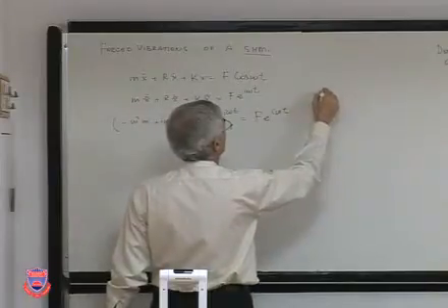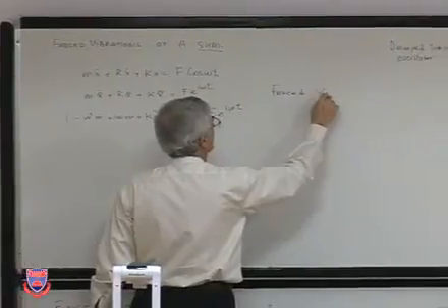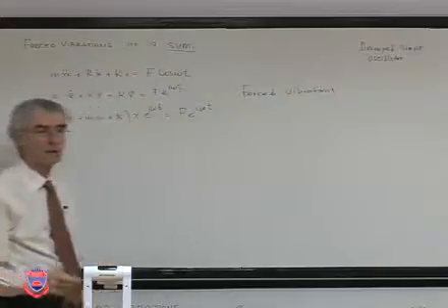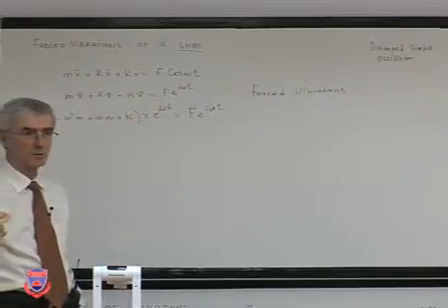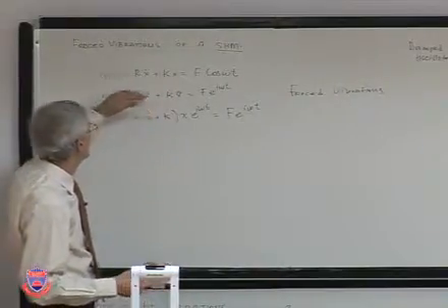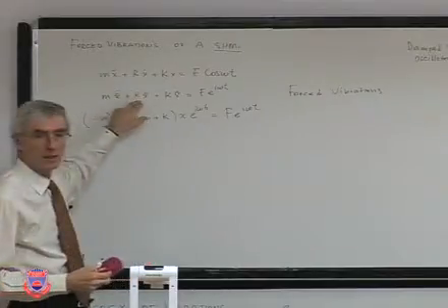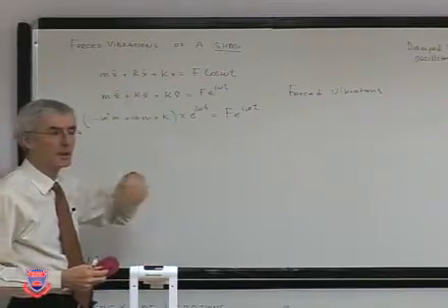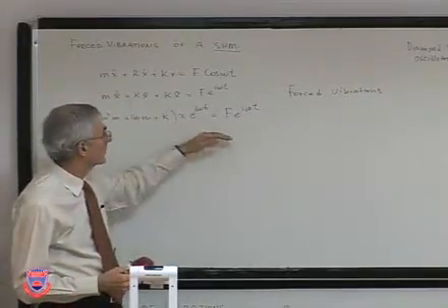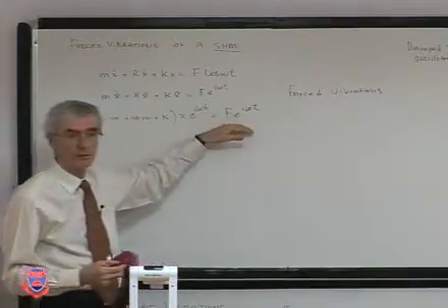Because it's a forced vibration problem. Technically, it has two solutions, a transient solution and a steady state solution. The transient solution is the one associated with its natural frequencies, but because there is damping in the system, it disappears in a very short time. So over the long time, it will be just the steady state vibrations, which must follow the force frequencies.